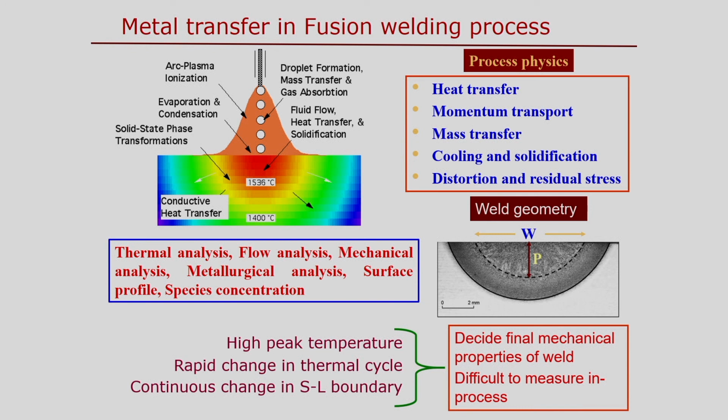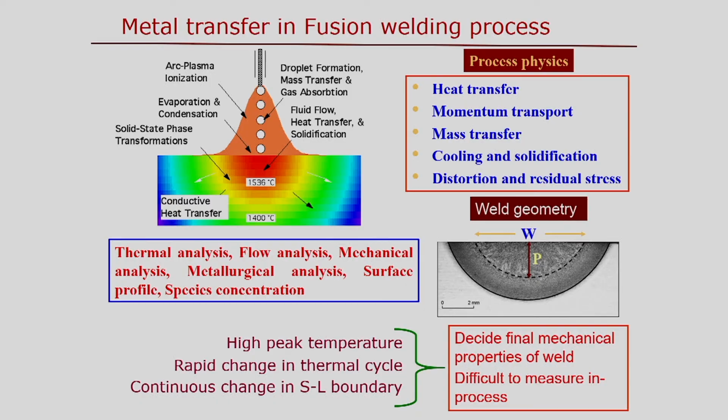Simple thermal analysis means we are interested only in the temperature profile or temperature distribution in a particular domain in the weld zone. So, that is only thermal analysis. If we do only fluid analysis, normally with thermofluid analysis, we need the information from the temperature. So, thermofluid analysis will give you the fluid flow field inside the molten pool, and this fluid flow analysis can be improved by incorporating the effect of the solidification behavior for a particular alloy system.